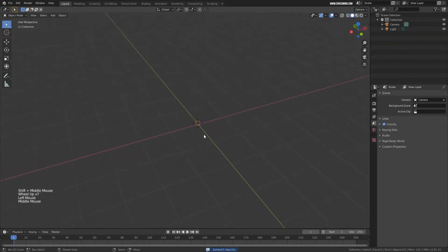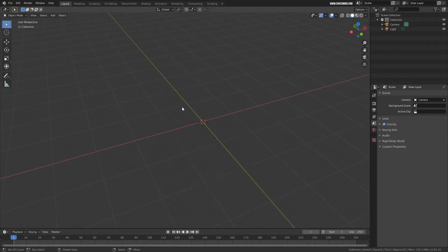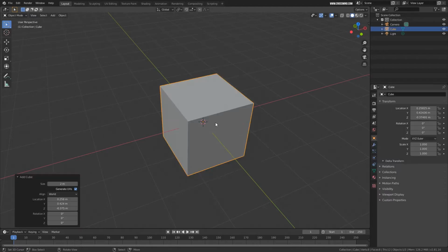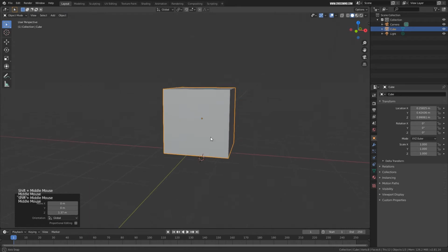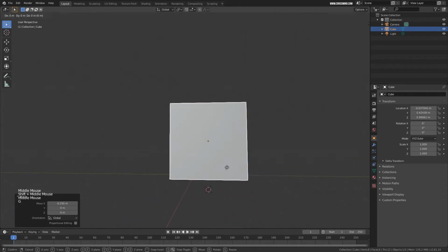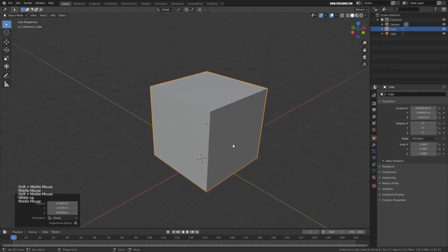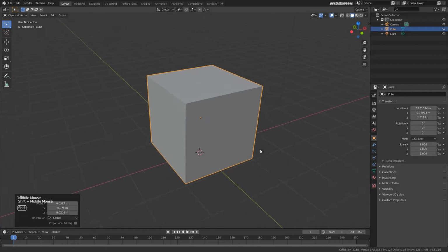Now let's talk about the smooth modifier. All right, before I talk about other tools in the object editing mode, I just want to explain how the low polygon geometry works with the smooth modifier, so that you know how to plan your mesh. Let's say I have a cube. All the time we will be creating objects in low polygon, very low resolution of mesh. You do not want to make your geometry way too smooth, so that it looks good, but it's not going to work for the animation if it's too heavy.